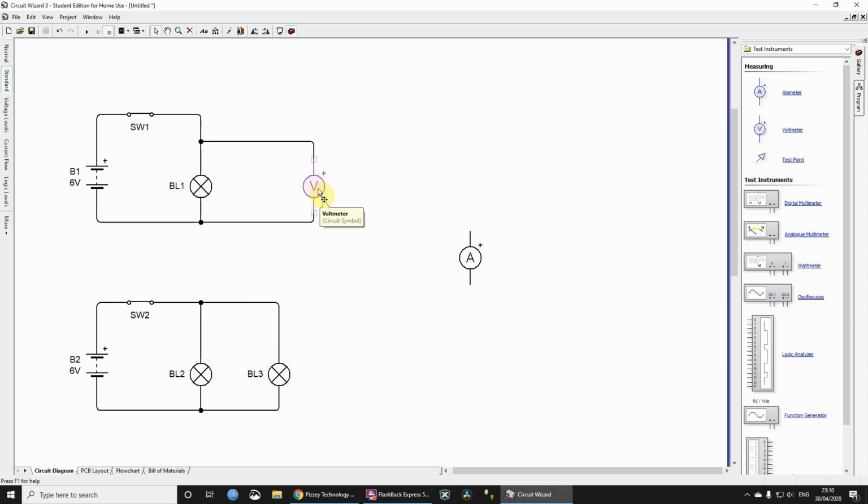You might be interested in doing something like this. Let's do Control L to rotate it. Would you like to guess? Remember, this is an optional task, and it doesn't matter if you do this or not, but would you like to guess what that voltage will be when we run the simulation? Well, it's 60 microvolts. It's more or less 0. Now, this switch has a resistance, therefore it has some voltage drop.